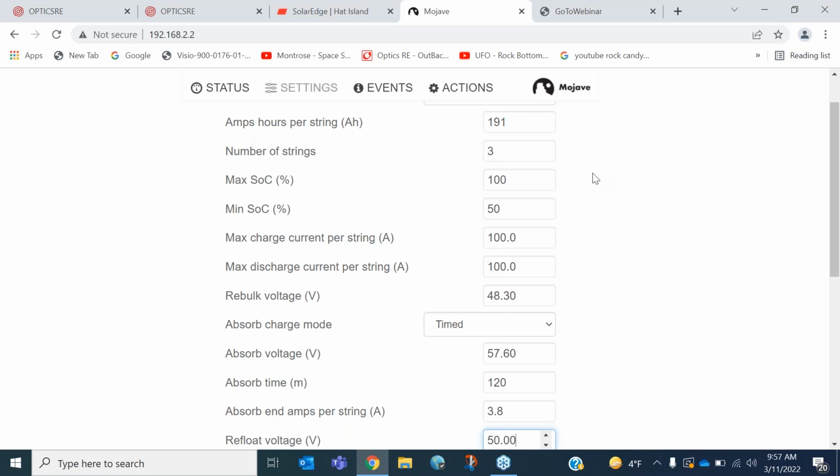Okay, and I think our last one here, does the AC couple breaker come factory installed, and if so, what is the amp rating? And some of these, I apologize from my point, you may have answered them, and it's very possible it went over my head. So if I'm asking anything that you've already answered, feel free to chime in on that. So the inverter output breaker, it's the 60 amp DIN rail that comes in the load center, and yes, that is a factory pre-wire.